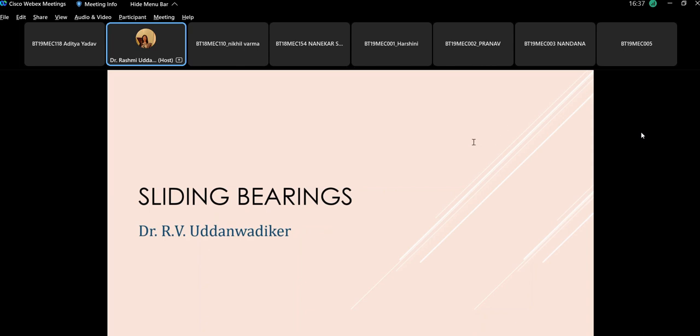What is your point, Dave? They restrict axial movement of parts. Movement will be restricted, yes. They will sustain axial forces along with the radial forces, but they will not let the shaft vibrate in the axial direction, right? This is your point, right? Yes, ma'am. Okay.